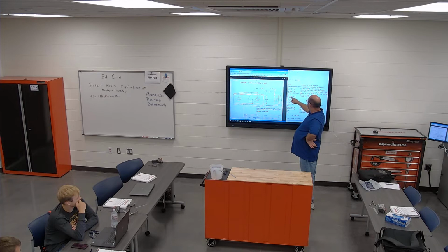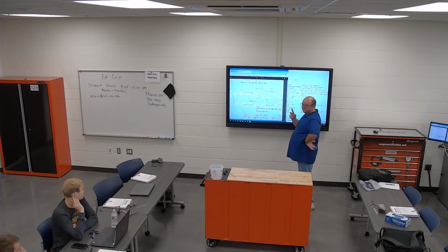G01, which is a cut move. Z of 0.1, because we don't rapid straight down in an unproven program. Feed rate of 25 inches a minute, and M08, which turns coolant on. So now we're going to go down to Z0. I did take one pass. And then an X of negative 5.5 and feed rate of 60 is what I put.